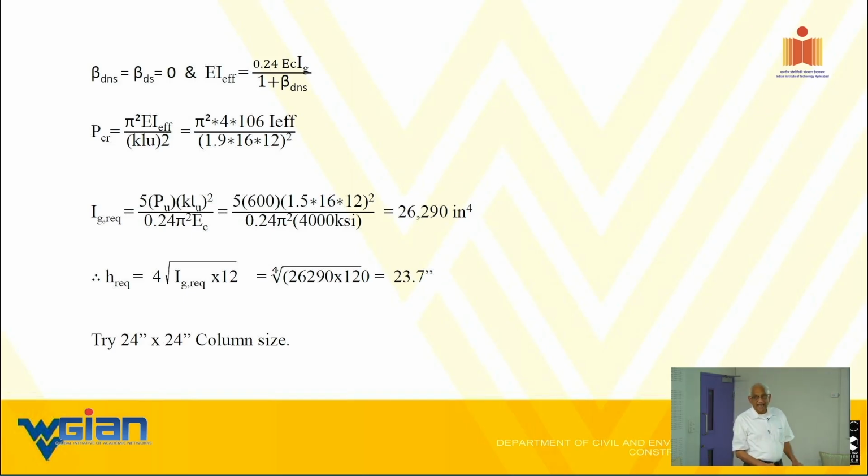So for a cracked section, we are going to assume 5 times the given load. That is where that 5 comes in. This is the given load after adding all your load factors. Okay. So that is the K factor.